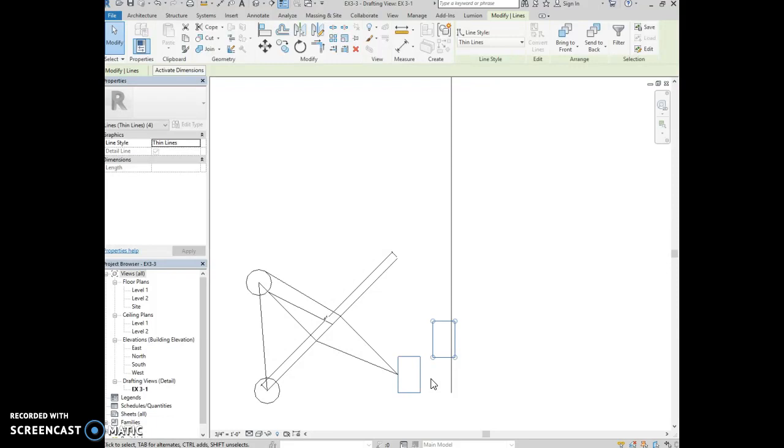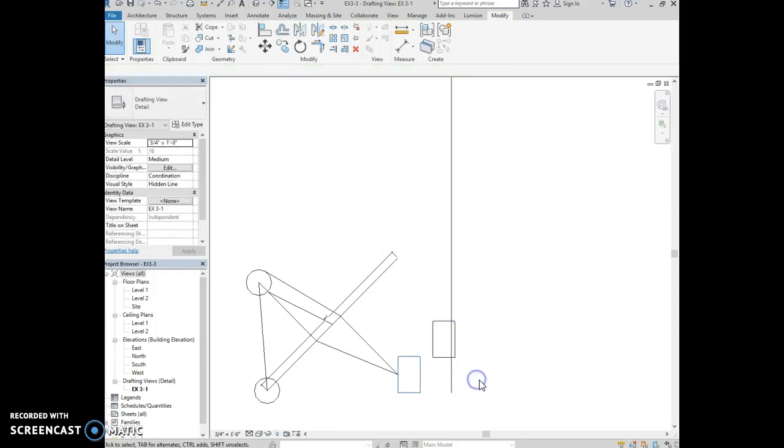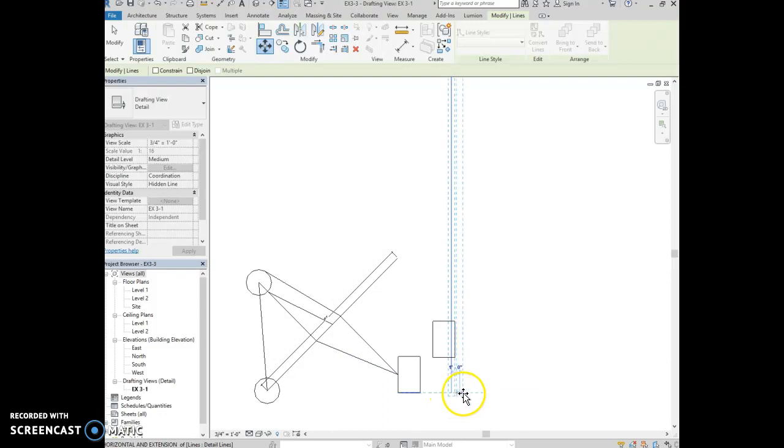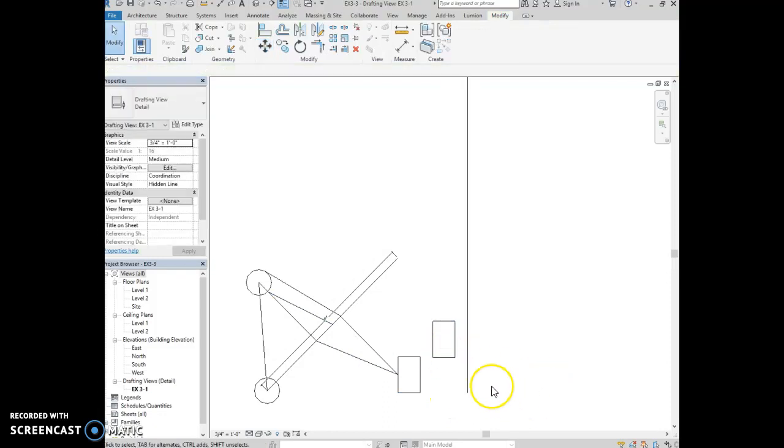So the move tool works exactly like the copy tool, except we're moving an object instead of copying it. So let's try to move something. Actually, let's move this line. Click the line, click move, select the endpoint. I'm just going to slide it over so it's not on top of the rectangle. If you don't have that line overlapping, maybe you could move another line or change something else that's overlapping in your drawing. Just practice with that move tool. You can always undo what you did if it's not following the exercise instructions.